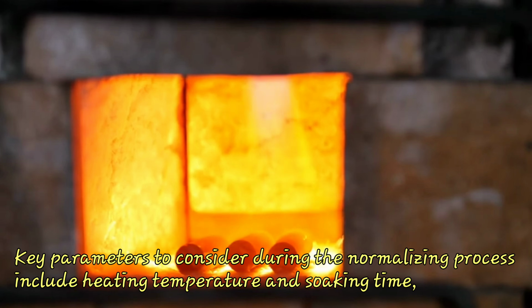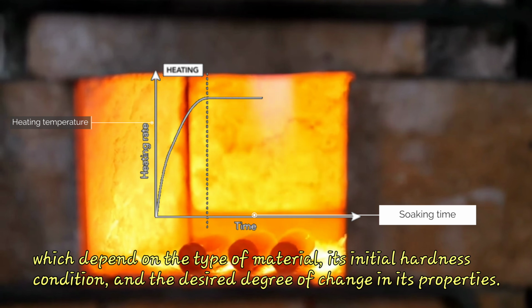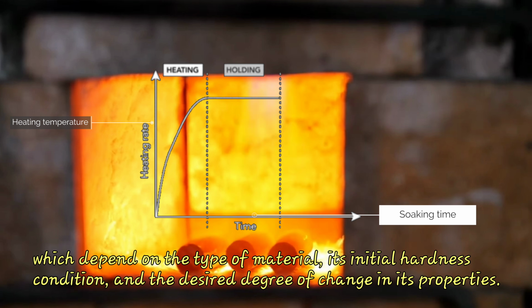Key parameters to consider during the normalizing process include heating temperature and soaking time, which depend on the type of material, its initial hardness condition, and the desired degree of change in its properties.